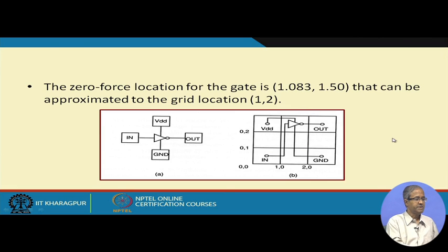Okay. So, this is the basic idea behind force directed placement. The sub problem that we looked at just now is that some other j number of blocks are already placed, and I am trying to place a new block I. What should be the coordinate of I such that the total force exerted on I by the external j blocks will be 0, both in the x direction and also in the y direction?